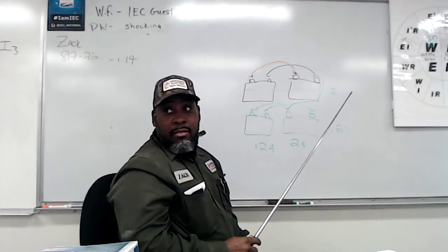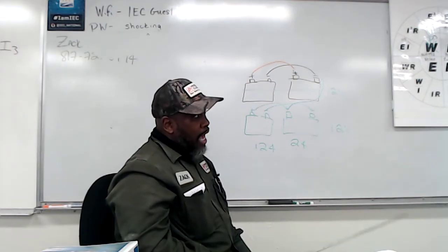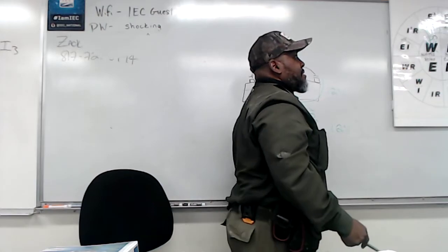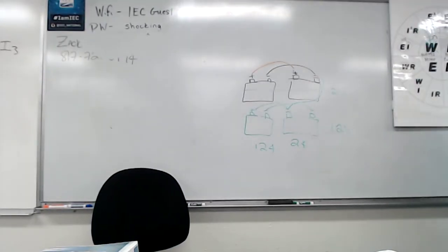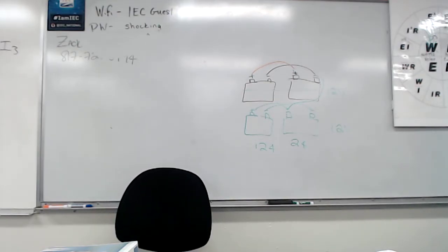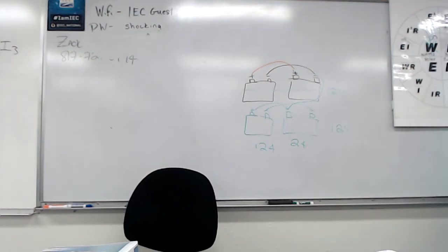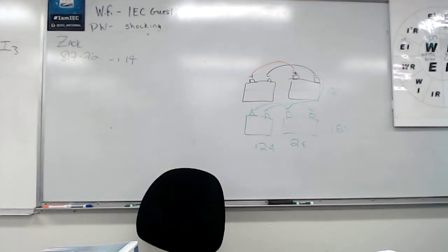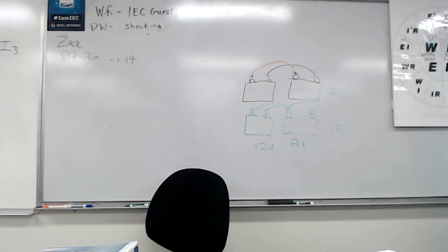So can you compare 3 and 1? I sure can. It just looks like this. It's the same thing, just turned. Right? This right here is in what? Plus to plus is what? Negative to negative is what? So then plus to minus is what? Series. And that's series. So these sets of parallel batteries give me 12 volts because they're in parallel, and this set, because they're in parallel, is 12 volts, plus this one will give me 24 volts. So actually 1 and 3 will work.